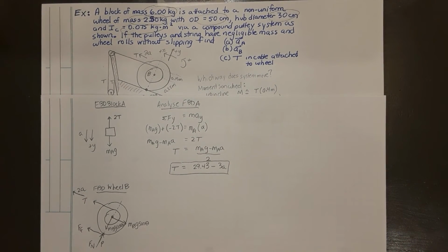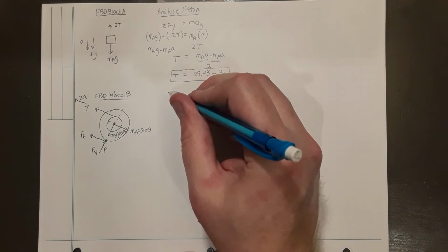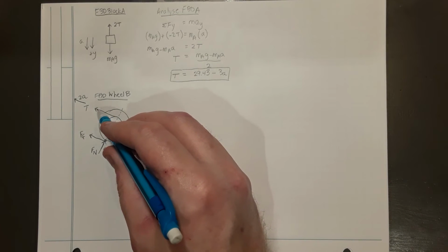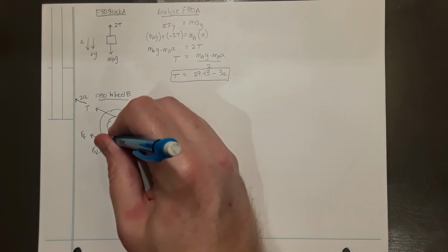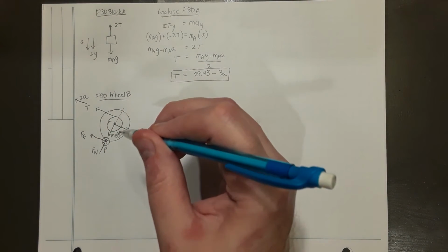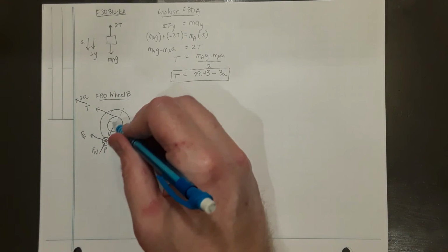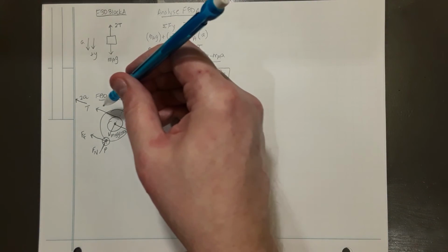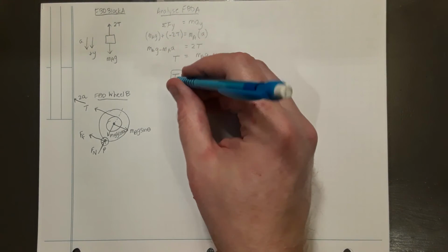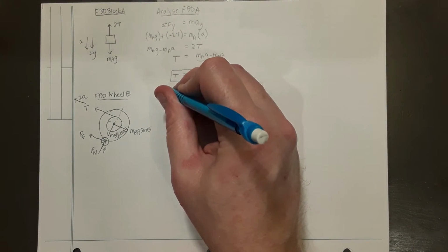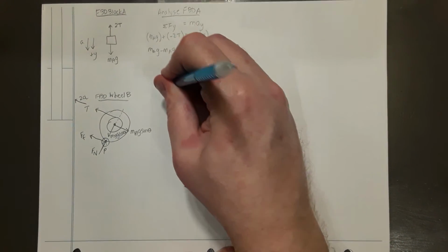In order to analyze this free body diagram, if we take net force in the x direction, we have tension unknown, acceleration unknown, and friction unknown. But if we take moments around axis P, it eliminates force of friction, normal force, and mBg cos theta from the analysis. Only 2 competing loads cause rotation around axis P. And in fact, the same 2 competing loads we introduced at the beginning when we tried to figure out which way the system moved.